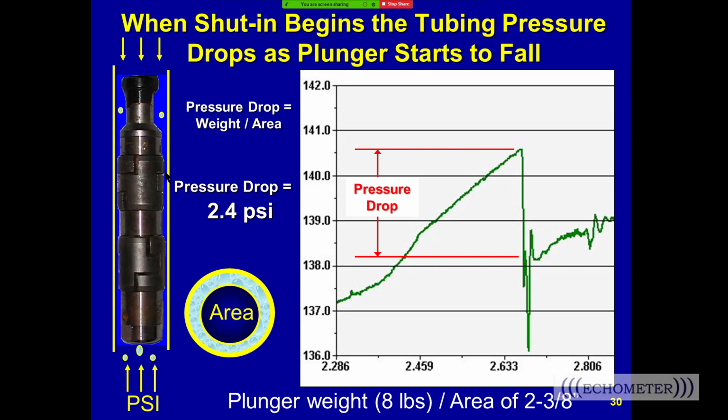And so the answer is, if you track the plunger frequently over an elapsed period of time, and you see the plunger performance coefficient changing, then that would indicate that the plunger is wearing out. So the answer is yes. We don't have any data where we've done that.